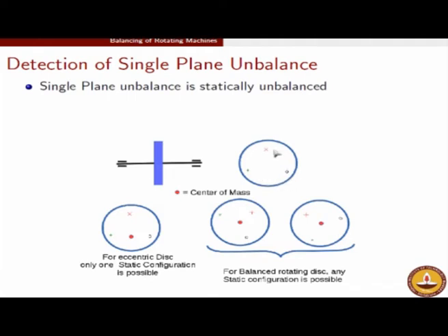If the mass is actually statically balanced, which means the center of mass is exactly the geometric center, then every time you repeat this experiment, you rotate the mass and let it take a static equilibrium configuration, you will get a random position of your marker. You will not get the same position of your marker. Every time you spin this disc, it will settle at some random position.